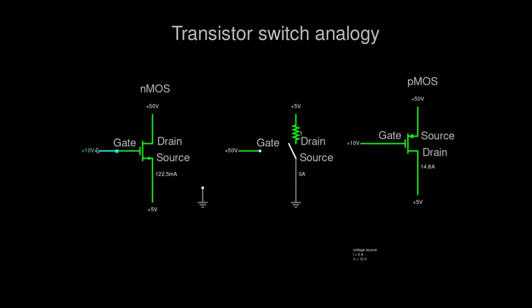Now, as it was in here, the gate voltage was supposed to be 1.5 volts higher than the source voltage. So in here, the source is higher, is upper, so the source voltage should be a threshold voltage higher than the gate voltage.